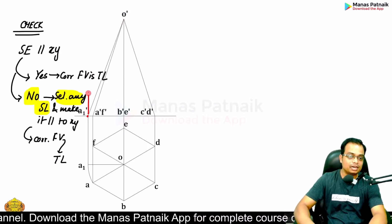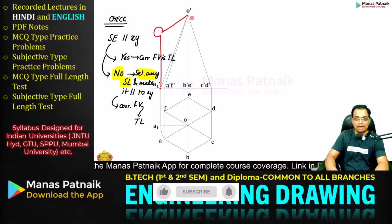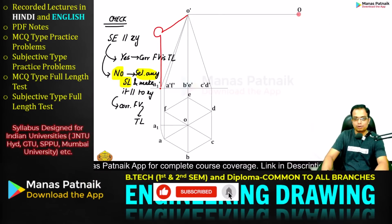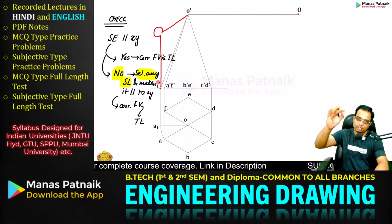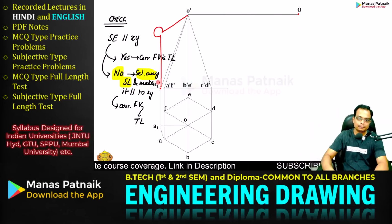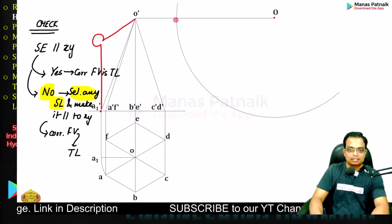So keep the pencil leg at A1 dash and the steel leg of your compass at O dash. Draw a line from over here. This point is marked as O. Now with this much as your radius, that is the true length of the slant edge, make an arc.